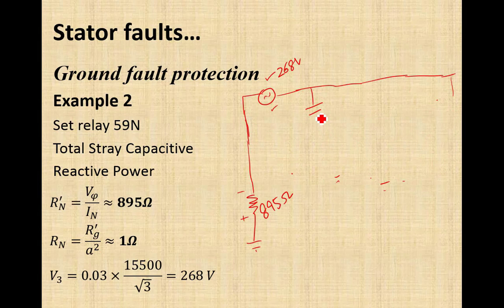Here the stray capacitance of generator winding, when all three combine together, is 0.66 microfarad. Then the stray capacitance of lightning arrestor will become 0.75 microfarad, now it is total for all three phases. Then the stray capacitance of the transformer will become 0.3 microfarad.